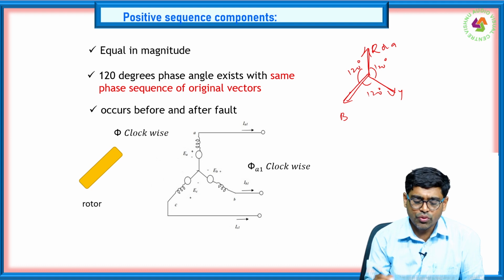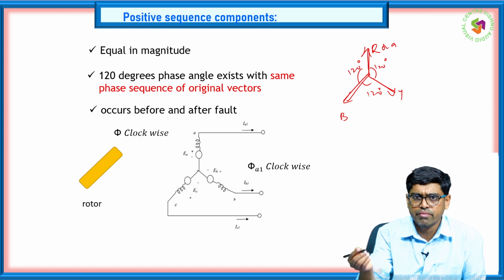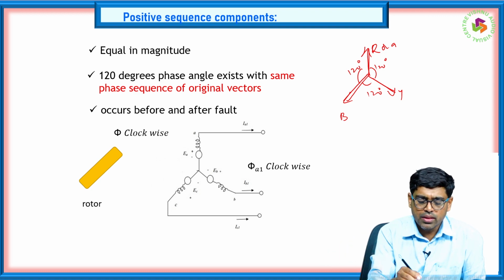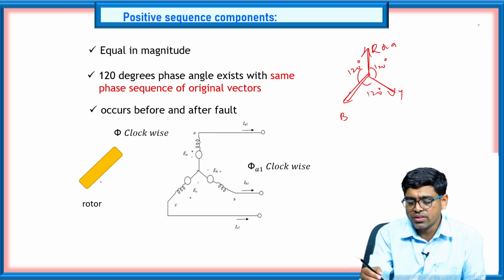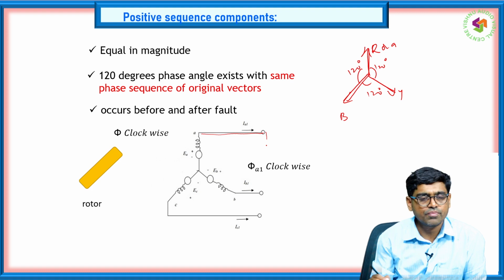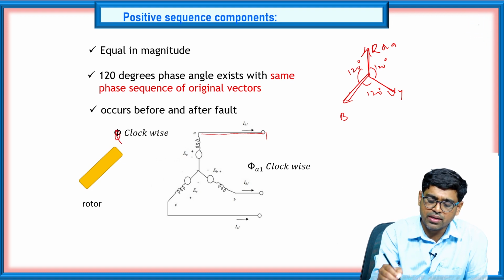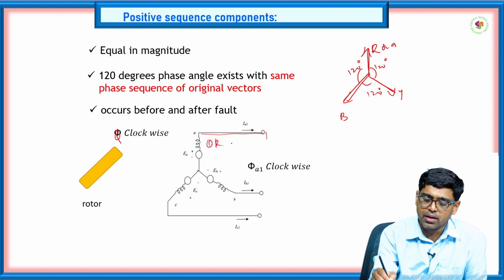So you can see that in our synchronous generator, the rotor is coupled with the stator. Whenever the rotor rotates, means the turbine, this rotor is connected to the turbine, and when the turbine rotates, the rotor rotates, then this rotor cuts the flux, then EMF is induced in the stator, and a current flow takes place like this. Due to this EMF we have the flux here, and then we have an induced EMF here, in R or maybe A phase, ER.